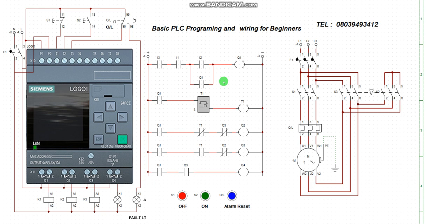Okay, but the major issue that you need to focus on is how to understand the function of this, how to also do your wiring from your PLC, having written your program from your TIA Portal, and you want to do the connection to your PLC CPU. Okay, so this is the most challenging aspect some of our trainees face. So you must know how to make this connection.